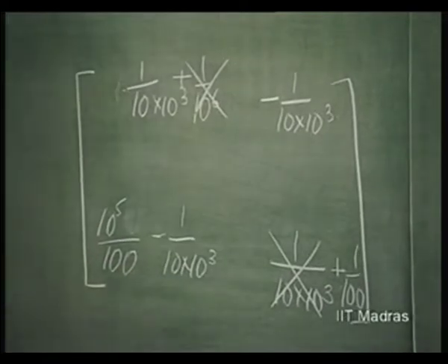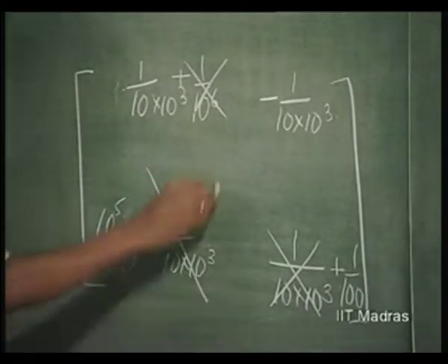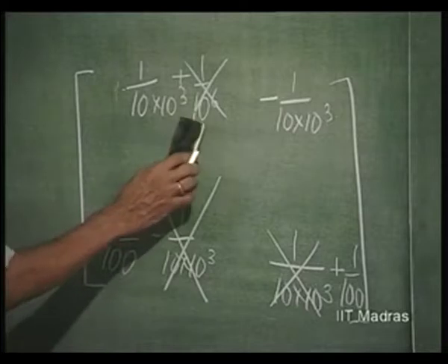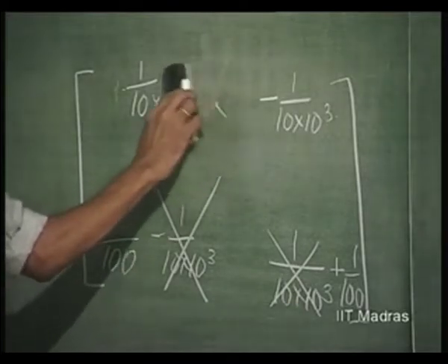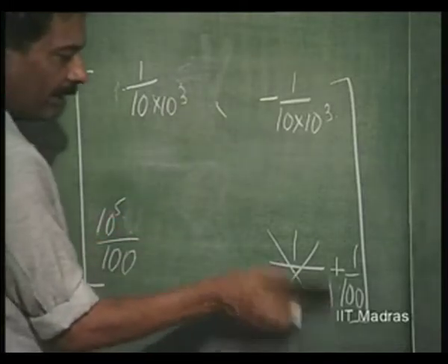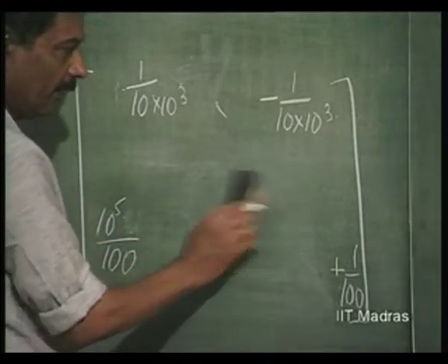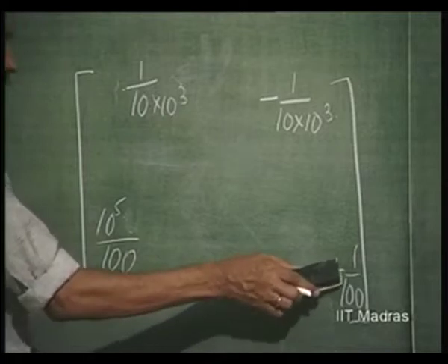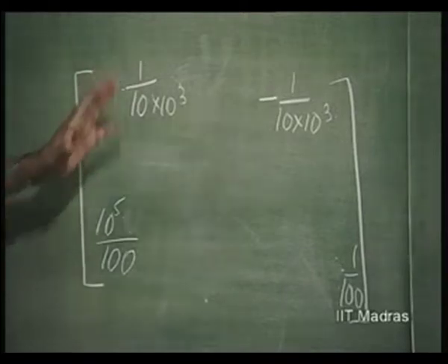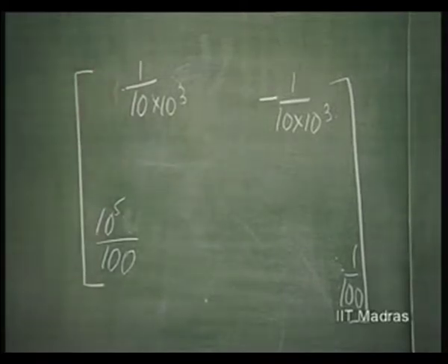So, you have this negligible compared to this, right. So, we will remove that, what is negligible. So, this matrix really helps you in coming up with the right type of approximation for the circuit. So, the composite Y parameter just becomes this. So, we can now find out the loop gain.